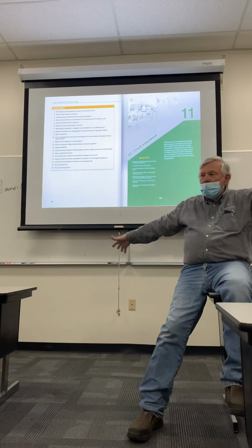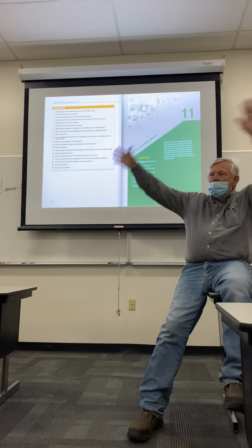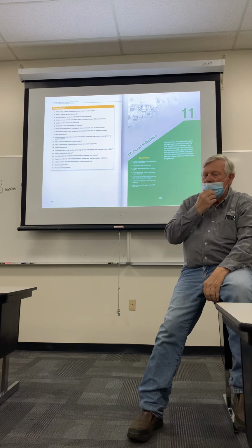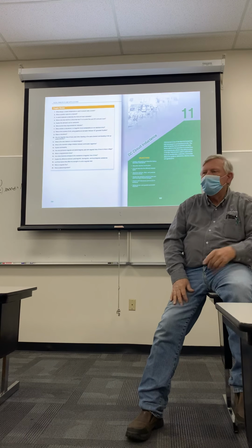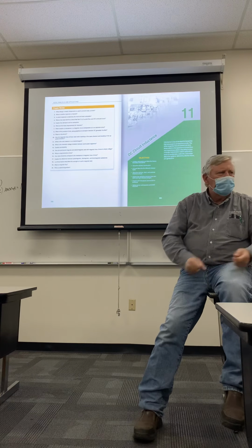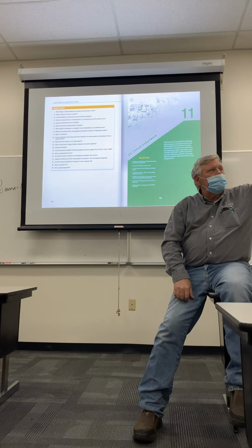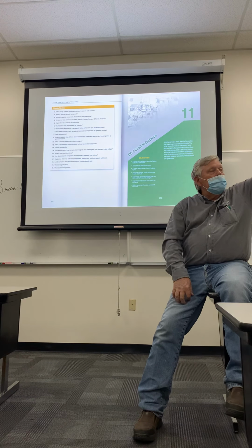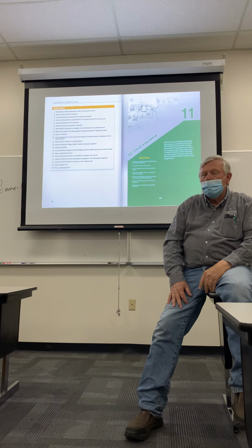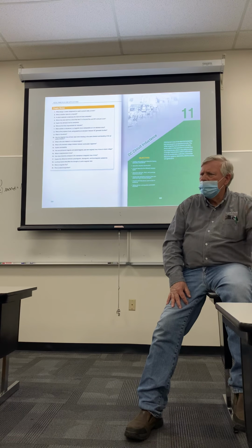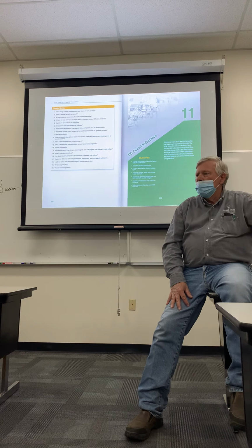Yeah, stop. I think his name was Roger. Roger, stop. I went running down through the building, and everybody was following me. And I ran over there and I said, stop, you're gonna electrocute yourself. And he kind of looked at me, went back to spraying. I was like, stop. He goes, what are you talking about? I said, that steam is gonna contact those 440 3-phase power lines up there, and it's gonna electrocute you. And he goes, water doesn't conduct electricity. Pure water doesn't conduct electricity. Steam is pure water. And there's no way that could shock me.